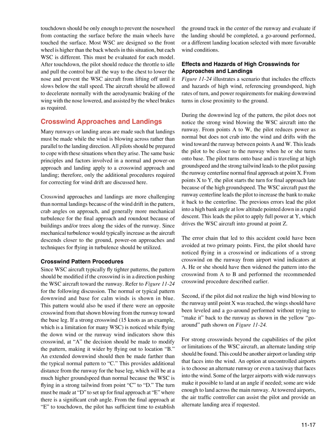Second, if the pilot did not realize the high wind blowing to the runway until point X was reached, the wings should have been leveled and a go-around performed without trying to make it back to the runway, as shown in the yellow go-around paths shown on Figure 1124.